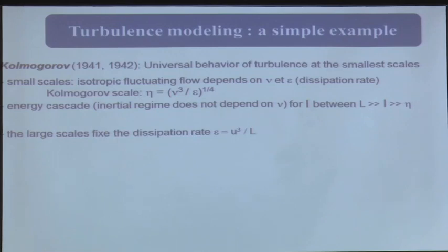So you see, this is the problem of fluid mechanics and turbulence more specifically: both the big and the smaller scales have a certain effect on the flow. The big ones are injecting energy and controlling the geometry of your flow and the relevance of your simulation. And the small eddies are in charge of dissipation. If you are not dissipating the energy, it will be contained in the rest of the flow, and then the flow will be different from reality. So this is really the main problem of fluid mechanics and turbulent flow.